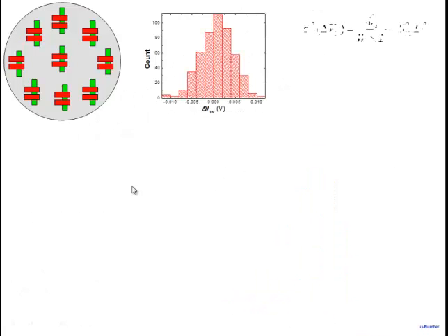All right. One of the important trends that people have observed is that if I look at the variance of the threshold voltage change, it goes as a constant factor times 1 over the area of the transistor. The larger the area of the transistor, the smaller the variance. So that is one dependence, the area dependence. The other dependence is the effective distance between the two transistors. There's a term which depends on the distance between the two transistors, and a term which is inversely proportional to the size.